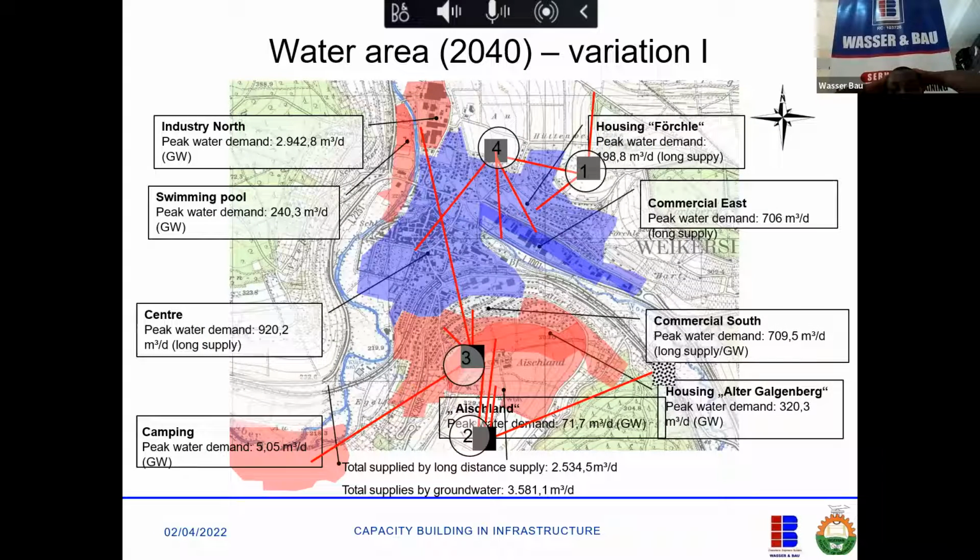So in designing your network, you look at the different areas: Garki, Gwarinpa, Lekki, Ikoyi, Lagos Island, and so on. You distribute them based on their population equivalent. You don't design based on one number. Even in an estate, you can design based on streets